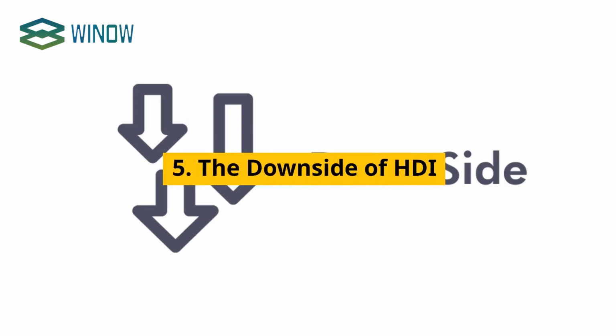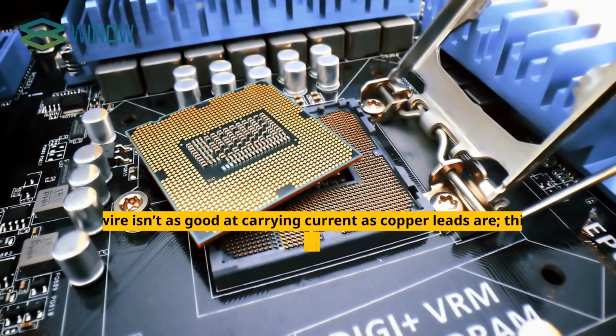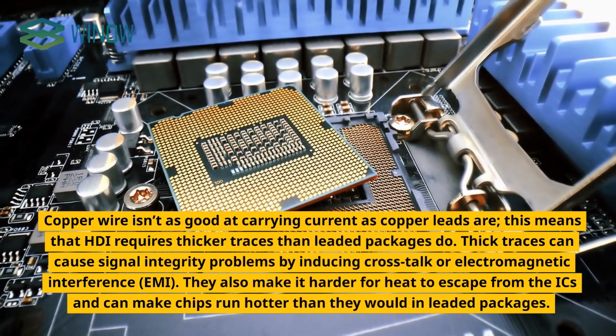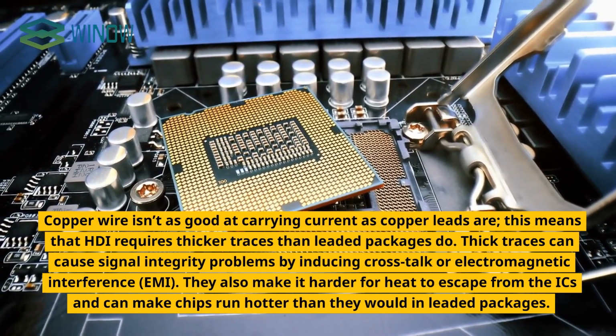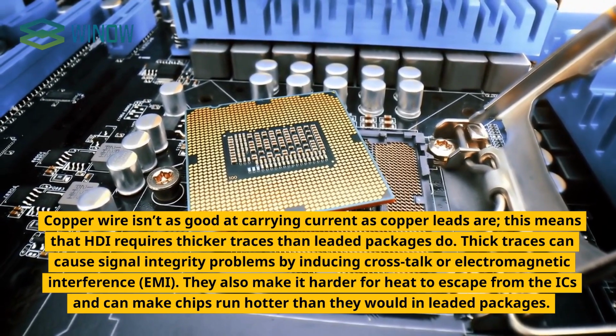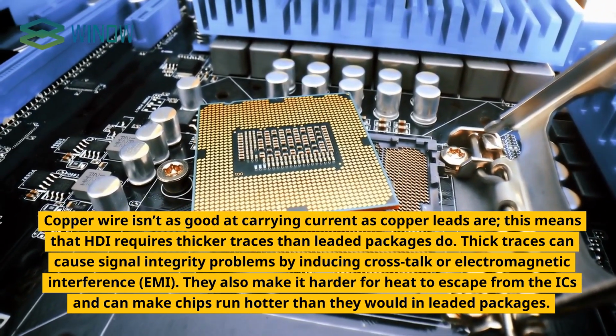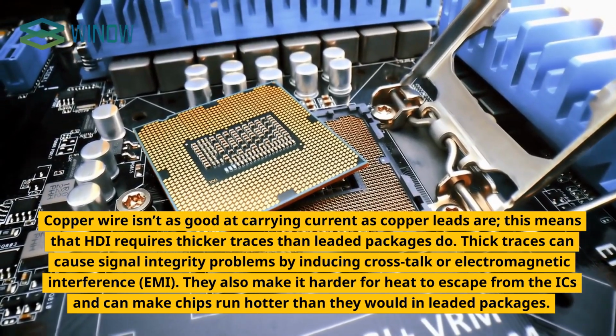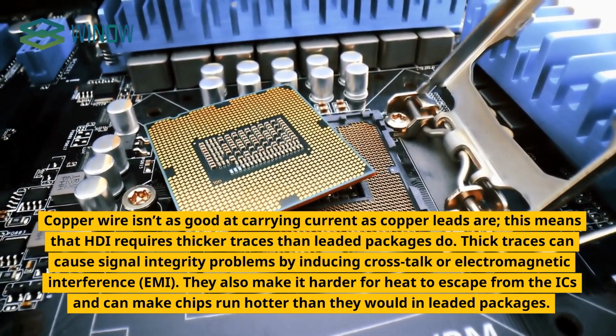5. The downside of HDI. Copper wire isn't as good at carrying current as copper leads are. This means that HDI requires thicker traces than leaded packages do. Thick traces can cause signal integrity problems by inducing crosstalk or electromagnetic interference, EMI. They also make it harder for heat to escape from the ICs and can make chips run hotter than they would in leaded packages. Conclusion.